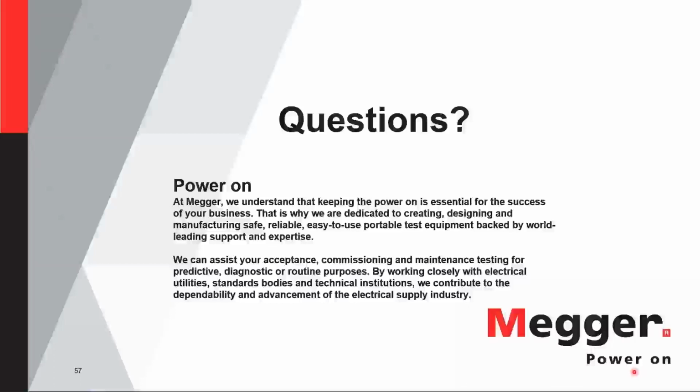Thank you, Daniel. Just one more addition to that question. If you were to take an oil sample, let's say the transformer was energized and you just took the oil sample and the transformer oil gauge tells you that the temperature is 45 or 50 degrees C, then you may get a different number, but there are just so many different factors that can affect your oil dielectric breakdown that it is always recommended to eliminate the temperature variable.